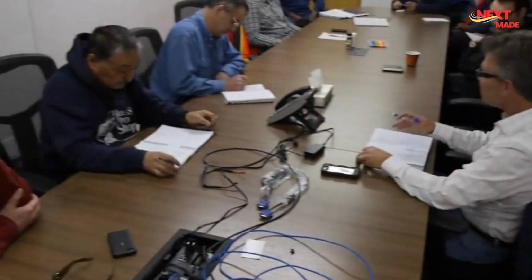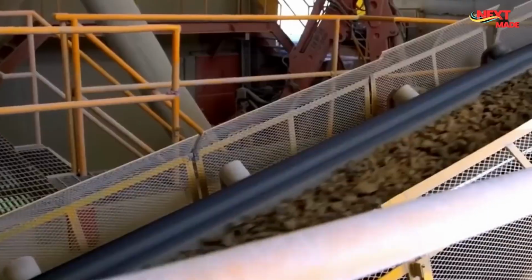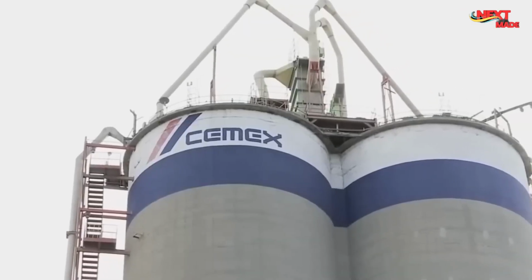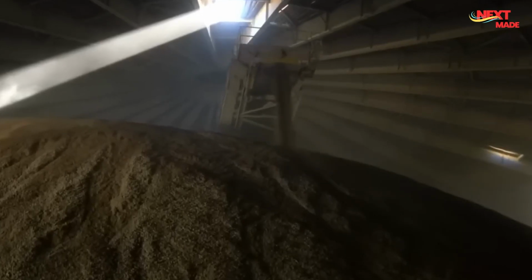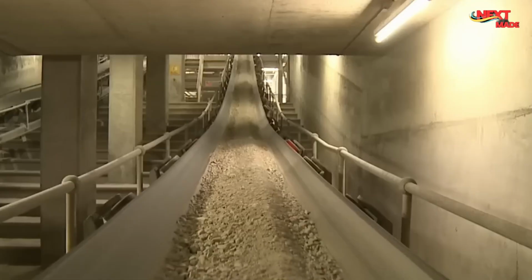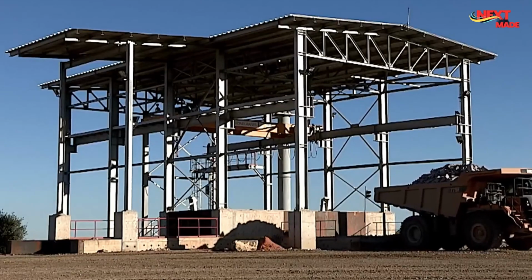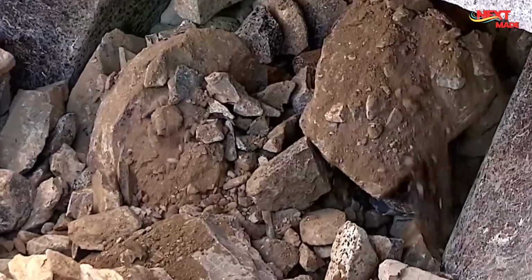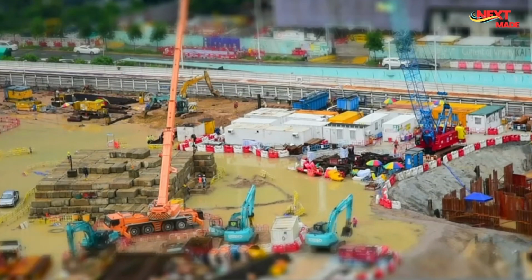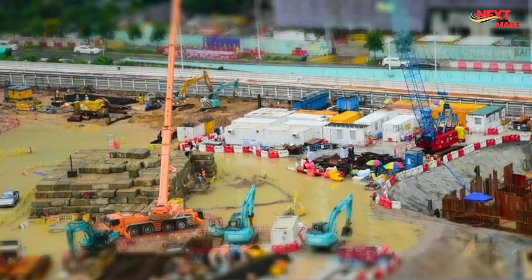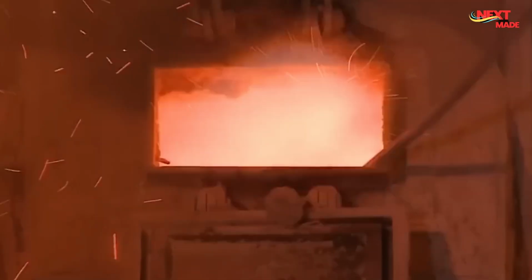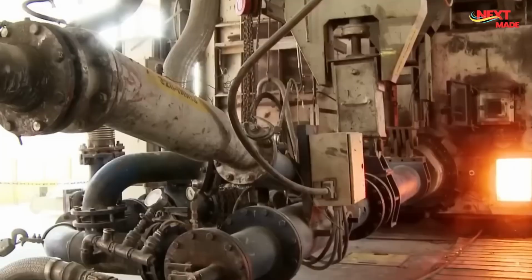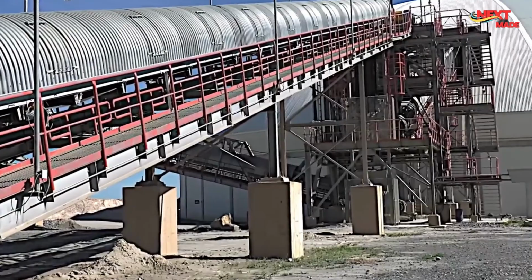The preheated and pre-calcined raw meal enters a rotary kiln, which is a long cylindrical furnace. The temperature in the kiln reaches around 1,450 degrees Celsius, or 2,642 degrees Fahrenheit. In the kiln, the raw materials undergo a series of complex chemical reactions, resulting in the formation of small marble-sized nodules called clinker. The clinker consists of calcium silicates, aluminates, and ferrites. The clinker is discharged from the kiln and passes through a clinker cooler where air is blown through it to reduce its temperature. Cooling the clinker is important to maintain its quality and prevent the formation of undesirable crystal formations.